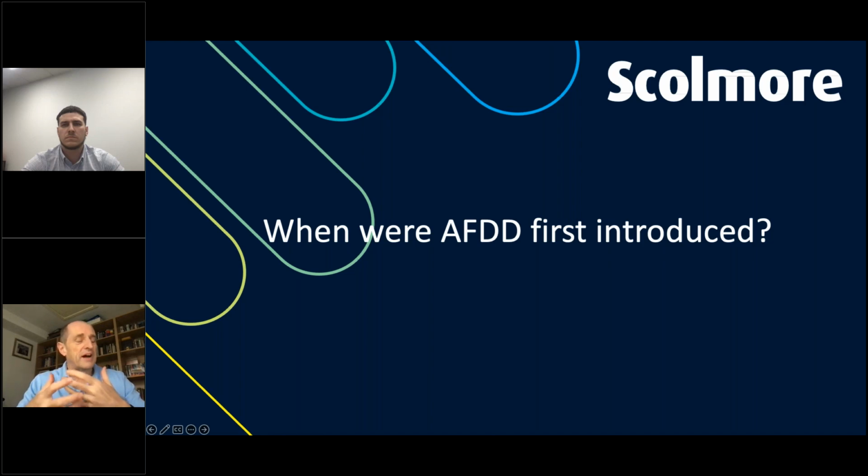It's an electronic device, though. It's monitoring the nature of signals within circuits, and it interacts with the means of circuit protection in that sense, rather than actually monitoring a physical event, such as an overload affecting a magnetic field or a resistive element. So it's quite different, but in effect, that's what an AFDD is.